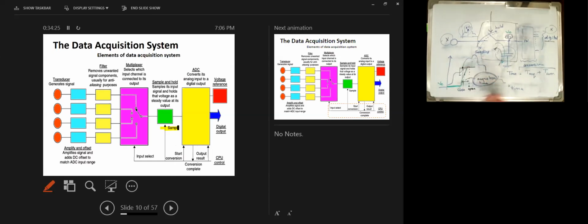So what does this time represent essentially? It is TS, the sampling period, because you need acquisition time and you need conversion time. So this is the time for one sample. Then you can repeat and take another sample. So this is TS, and if this is TS, then this is essentially 1 over Fs. So this is the sampling period of your system, or in other words, the sampling frequency of your system.